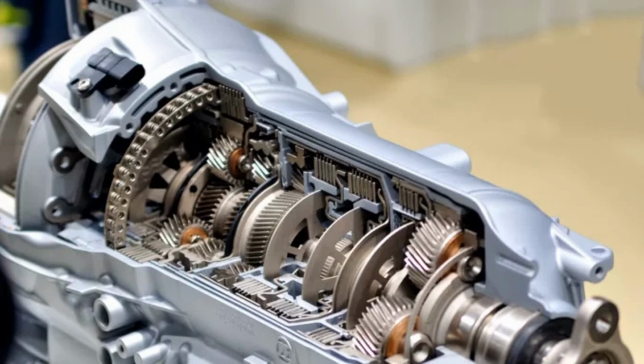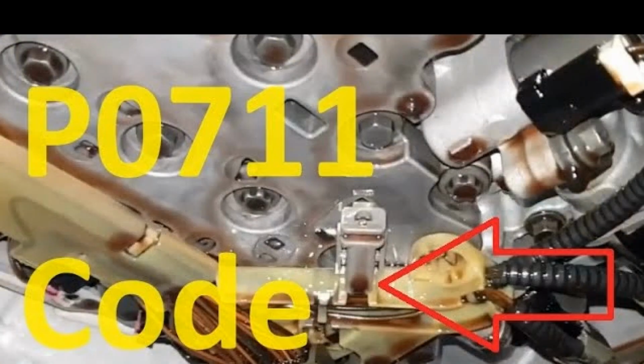Code P0711 is set when the PCM identifies a signal from the transmission temperature sensor that does not match the expected values. On a GM vehicle, the conditions for triggering code P0711 are as follows. Condition 1: a transmission fluid temperature at startup of minus 40 to plus 20 degrees Celsius (minus 40 to plus 68 degrees Fahrenheit). Vehicle speed exceeds 8 km per hour (5 miles per hour) for a cumulative 300 seconds (5 minutes). Transmission fluid temperature has not varied by more than 2 degrees Celsius (4 degrees Fahrenheit) since startup for 80 seconds.